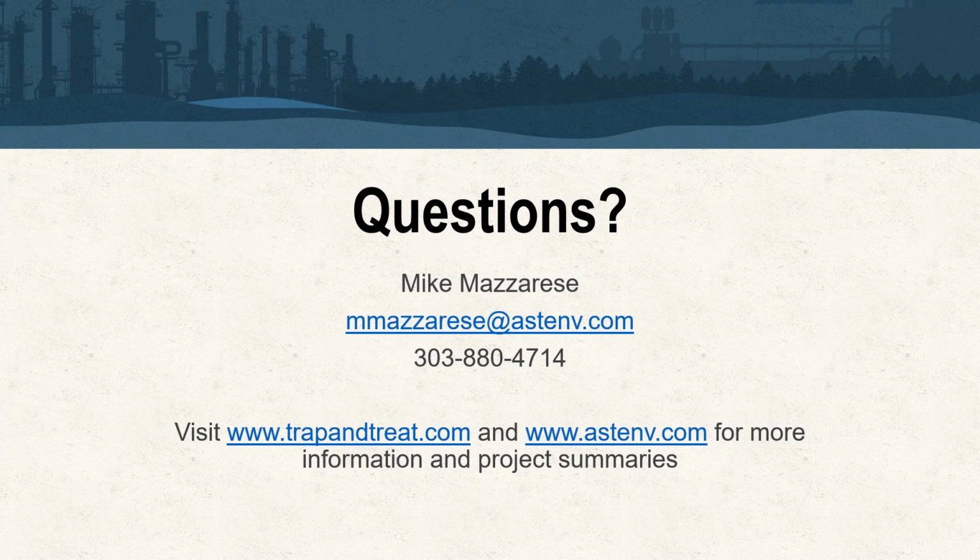For example, besides dissolved gases, like acetylene and ethylene, there are volatile fatty acids and anions, so sulfate, nitrate, the additives that are included with BOS 200, or chloride. So you get a pretty long suite of analyses that are specific to these technologies that we cover today and will cover next week. As part of that effort, we grab groundwaters as part of the baseline too, to make sure we have baseline values for all those constituents. And as often as you want to send groundwater samples to the RPI lab, they will run them post project as well.